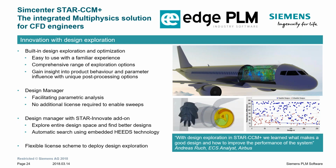Users can take it one step further with Star Innovate, which is an add-on, and perform single and multi-objective optimization studies to intelligently search the design space using the same tried and proven technology found in HEEDS, MBO. Now, HEEDS stands for Hierarchical Evolutionary Engineering Design System. It also provides stochastic analysis to help engineers determine the sensitivity of their simulation predictions to small changes in input parameters, such as manufacturing tolerances or fluctuations in boundary condition values.